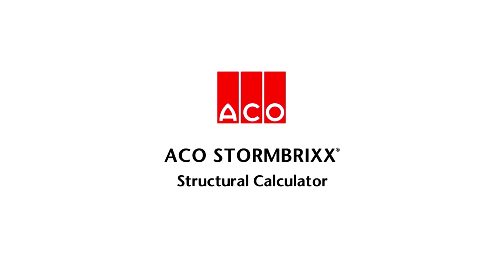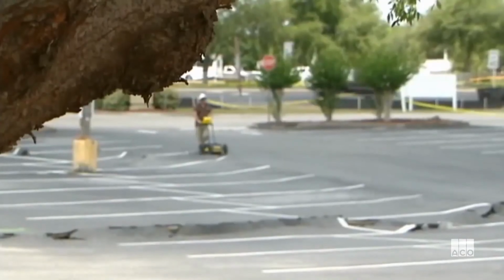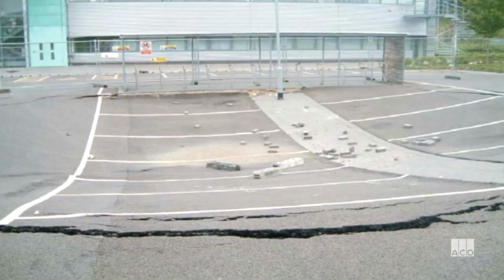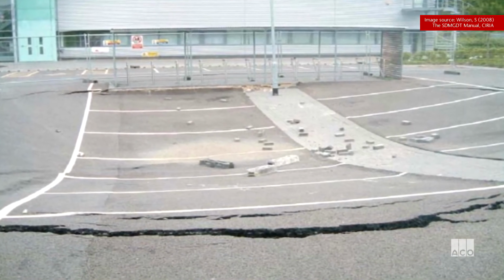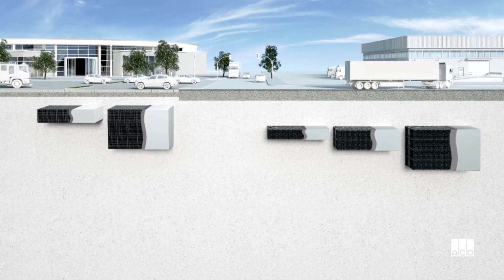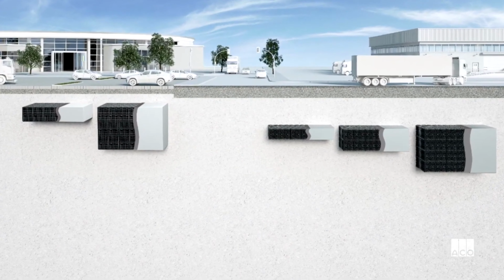In Australia, there are no standards governing the structural integrity of geocellular plastic tanks, meaning that there are no industry guidelines for the strength and durability of these underground structures. This places a heavy burden on designers and engineers who will need to trust manufacturers and then make their own assessment. When considering loads imposed on a tank, engineers must account for both long and short-term loads.